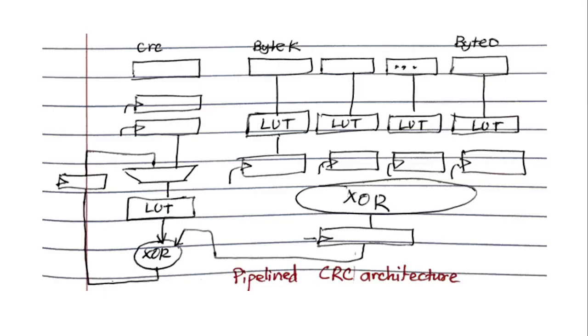Okay, so next, it's the same function here. What we have done is that instead of the XOR functions that we saw, we have now lookup tables. And these lookup tables know exactly, this is not the same lookup table, because for byte 0, I know that this byte is not having zeros after it. This is the last byte, so there is nothing following it, right?